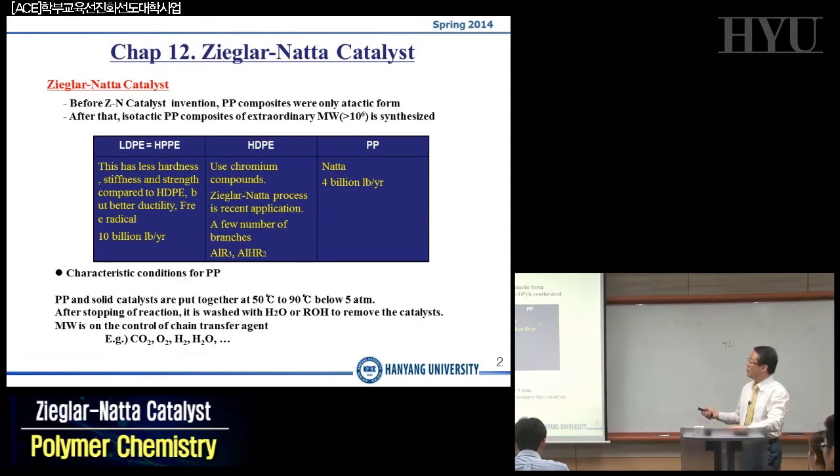And if you think about polypropylene, you have three very different tactic systems, right? Tacticity is exemplified by polypropylene, where the methyl units in your side chain could be in a random way, which is called atactic, or could be in the same position, which is called isotactic, or alternating, which is syndiotactic.